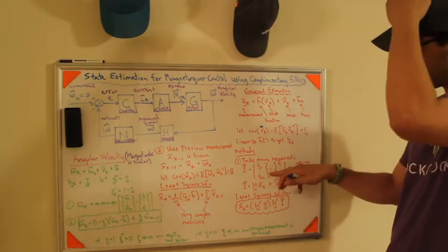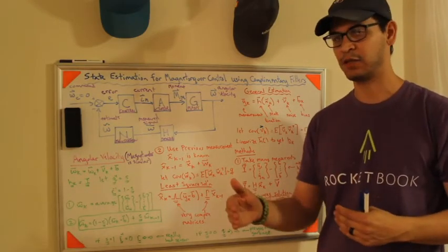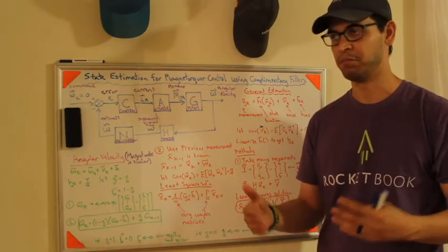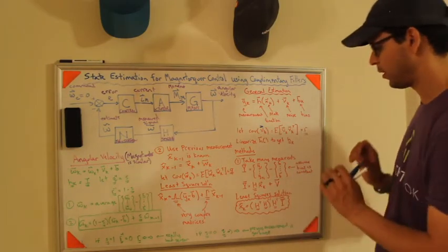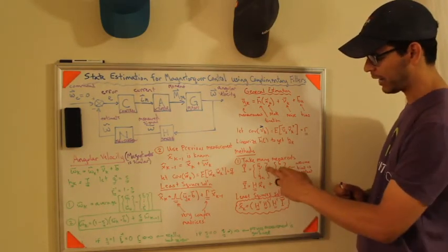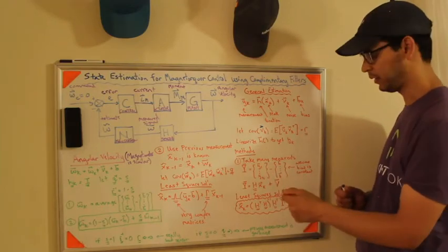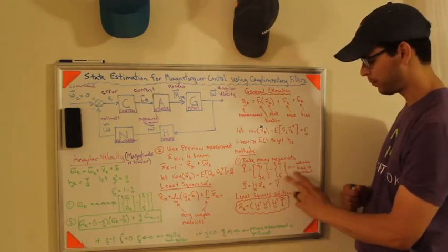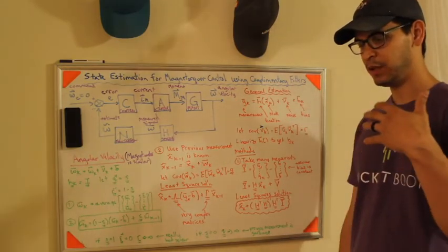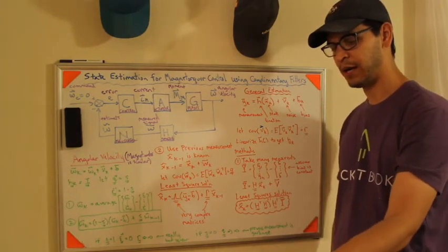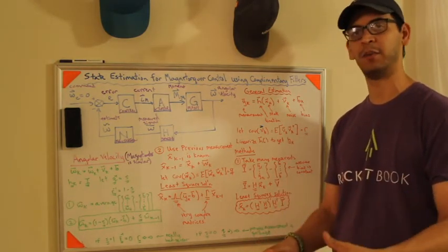The idea with taking these measurements is, if you have a sensor that's really fast, say you can get 100 measurements in a tenth of a second, I would recommend doing it. Every tenth of a second, take 100 measurements and then throw it into this algorithm. You're going to get all of the measurements that you got in that fraction of a second. And at least for this algorithm, you have to assume you know the bias. That assumes that you've put the sensor on the ground, shielded it from any external disturbances, taken data and measured the bias.